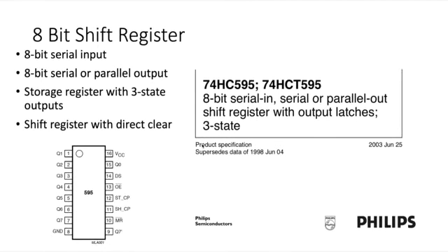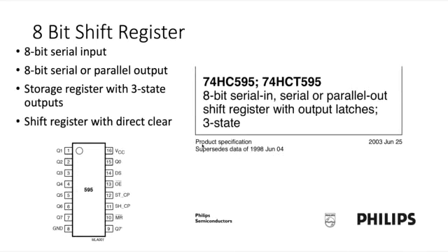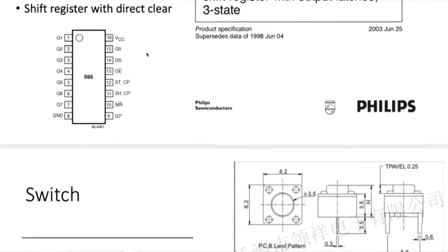A shift register is an interesting device where you can be collecting 8 bits of information, and basically if you have another bit of information come in, the bit at the other end goes away. So it's like a memory device that can be clocked, and those things are shifted each time you get a clock. And we can talk more about that later.